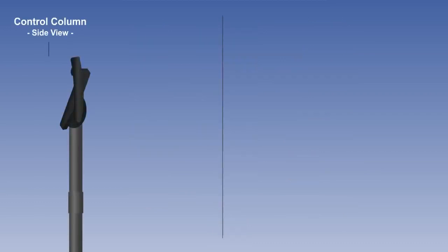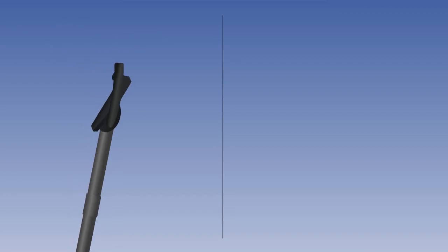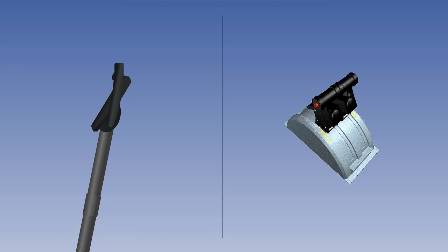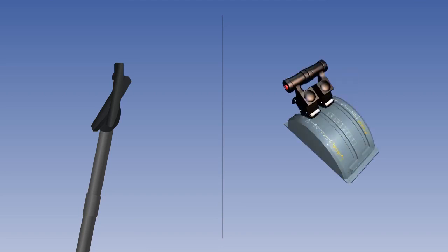A stall protection system differs from the stall warning system only in that it is triggered at a later stage than the stall warning, and it has different outputs. In a traditional aeroplane, we have the stick push, whereas in more modern aeroplanes, we have an output to the auto throttles, which move them to take-off go-around thrust.